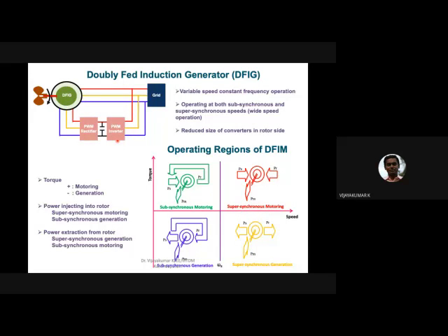Even if you have any power electronic switch in the system, obviously it will pollute the supply. So for that, we have to go with active filters and passive filters. Again, we have to go with the design of the filters, right? That's another design aspect. But to avoid connecting the inverter directly to the grid, we have proposed a new topology.